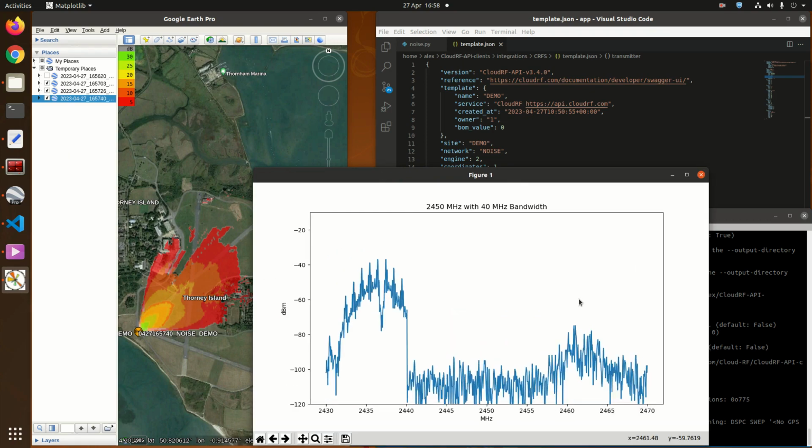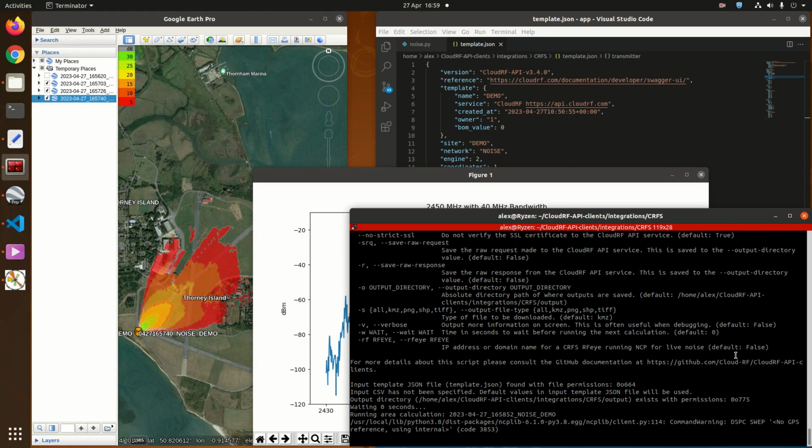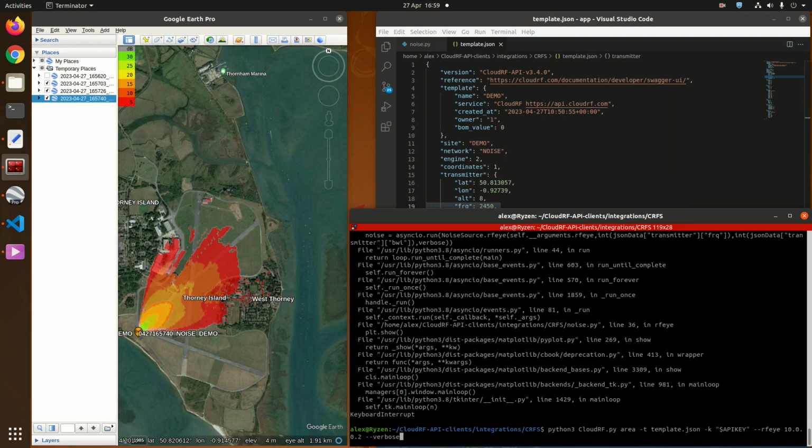So signals will bring up the noise floor and they will impact your modeling. With this API client, you can now connect to an RFeye and perform accurate modeling using measured noise floor values. The beauty of the RFeye is it's a network-based receiver, so you could conduct modeling with accurate values in a distant location without actually visiting there to take a noise floor measurement.